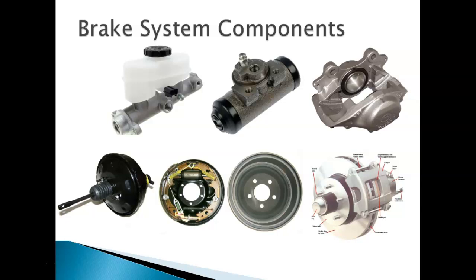And then you've got the caliper, and inside the caliper is where your brakes sit. You have your brake fluid reservoir, which again, you need to make sure that whenever you work on your brakes, you bleed them off. Bleed out any air that's in them.